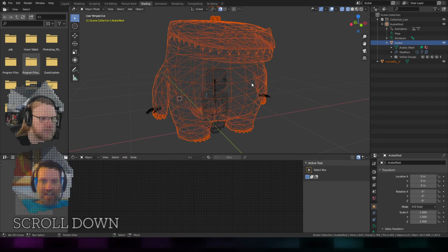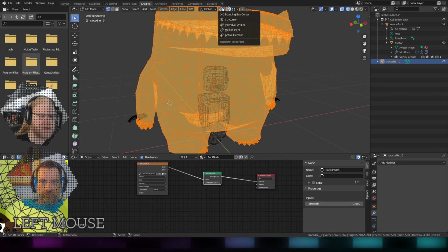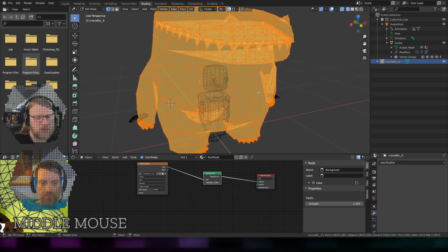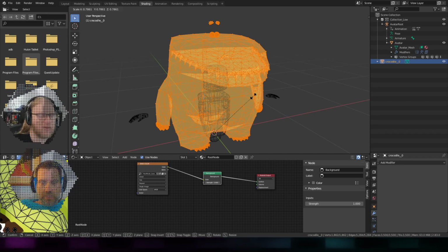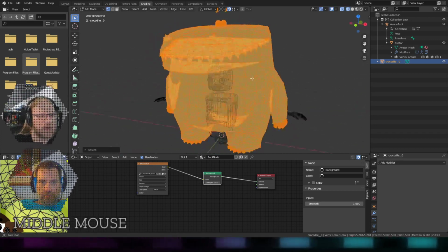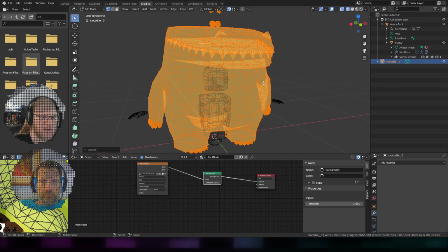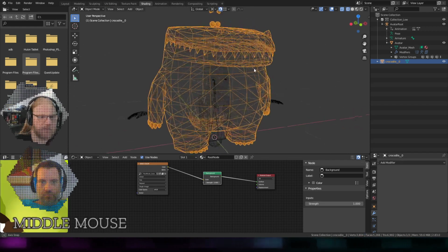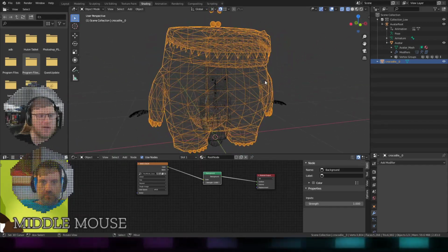But you could still decide, like, I don't know. Yeah, the actual vertical position of the avatar we basically ignore because we position it based on the head position. So wherever the head is going to be at eye height, or actually between the two eye bones, is where we will position the camera, and that's where your avatar's height is going to be. So it's convenient for modeling to line that up in Blender as well, just for your own convenience. But we don't actually care where it is.